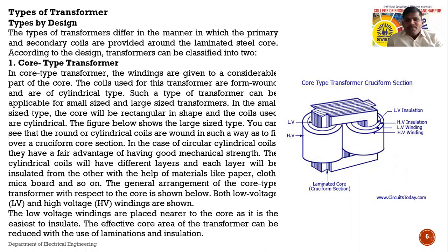Do you know that the transformer tank is totally filled with oil? Totally filled with oil. And this oil acts as an insulating material from winding to winding, from core to winding also, and for turns insulation, some types of coating can be used, like varnish.